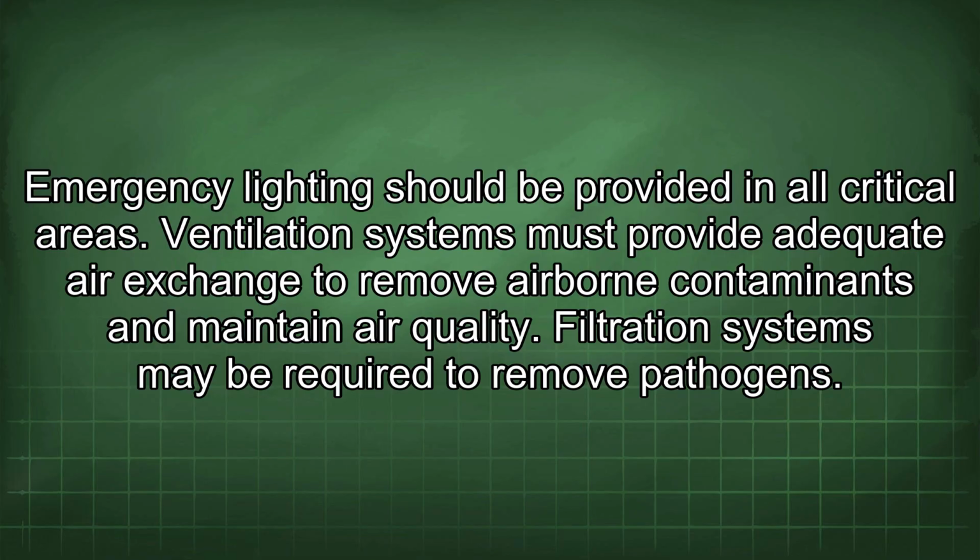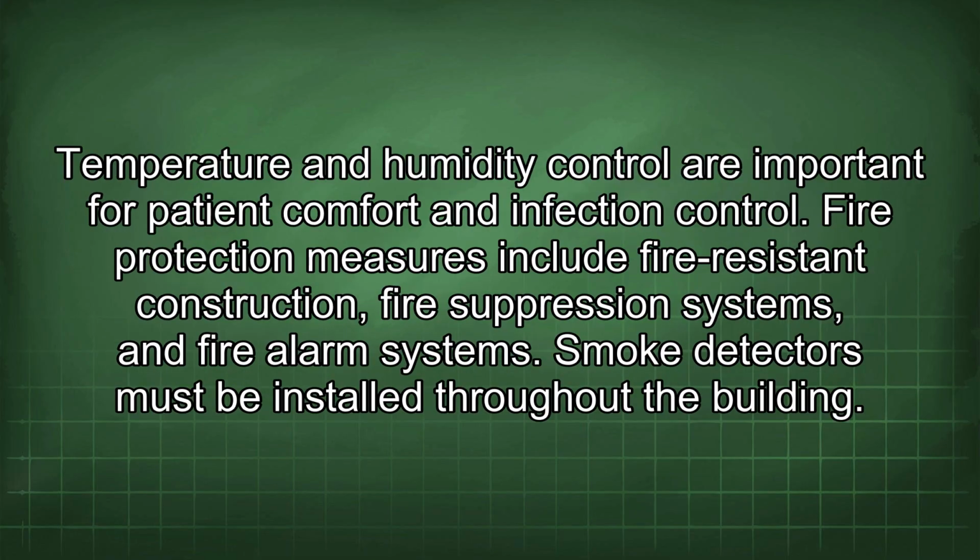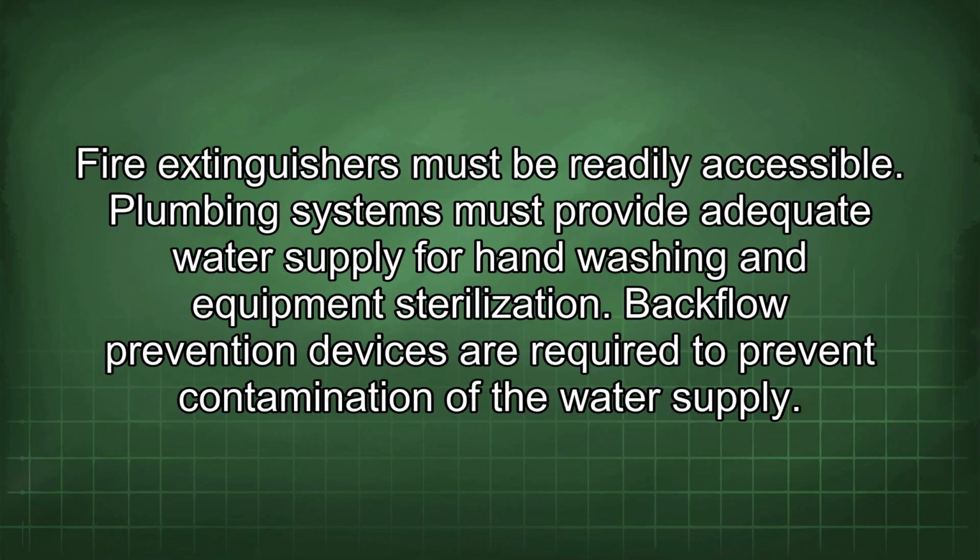Ventilation systems must provide adequate air exchange to remove airborne contaminants and maintain air quality. Filtration systems may be required to remove pathogens. Temperature and humidity control are important for patient comfort and infection control. Fire protection measures include fire-resistant construction, fire suppression systems, and fire alarm systems. Smoke detectors must be installed throughout the building. Fire extinguishers must be readily accessible.